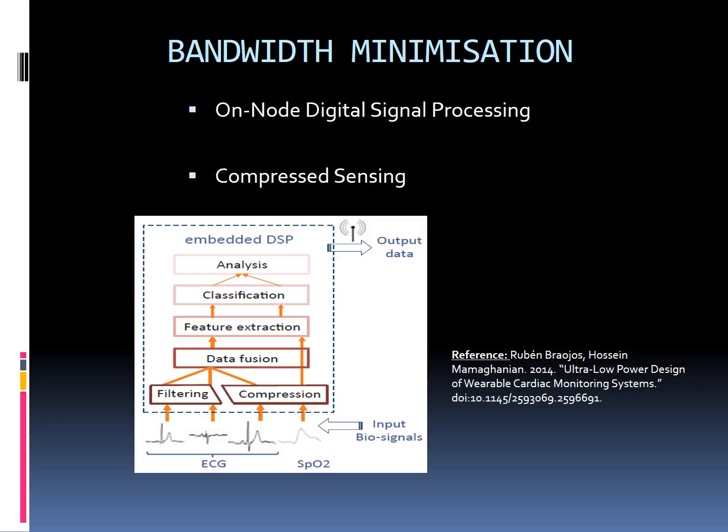Streaming the raw data directly to the external server through a wireless link might consume a lot of bandwidth, thereby wasting power. Instead, only the data that is needed can be extracted by performing on-node signal processing at various levels of abstraction. After extracting, only the useful data will be transmitted, thus decreasing the bandwidths of the wireless links through which the data will be passed, which in turn will enhance the energy efficiency.